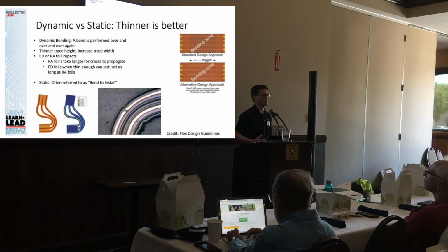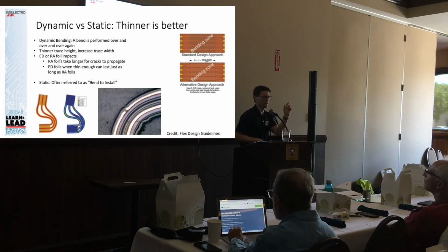So how do we solve some of our electrical issues? Maybe we need to have a certain amount of energy going through those flex cables. Maybe we are at such a high transmission rate that we can't make our traces as thin as we want. Thin the trace out, make it a little bit wider. And that does two things. One, it gives you a wider surface area. So if we all remember what stress is, it's force over area. We get a larger cross-sectional area of the copper, which means we have less stress being applied to the copper, and hence we won't get to its yield strength before too long, hopefully. But then it also can help us because we can get a tighter coupling to ground and we can actually get better signal integrity.